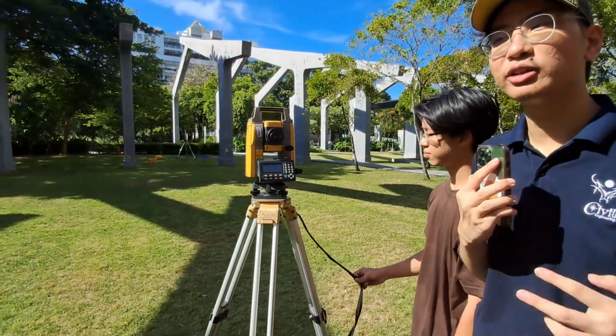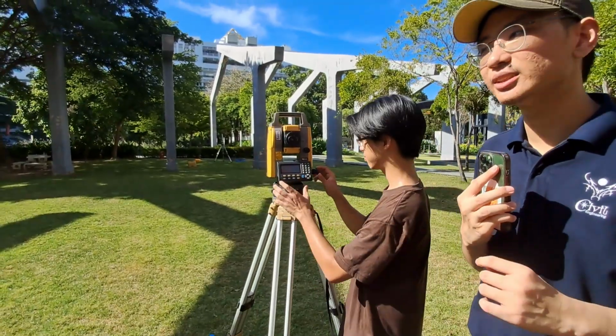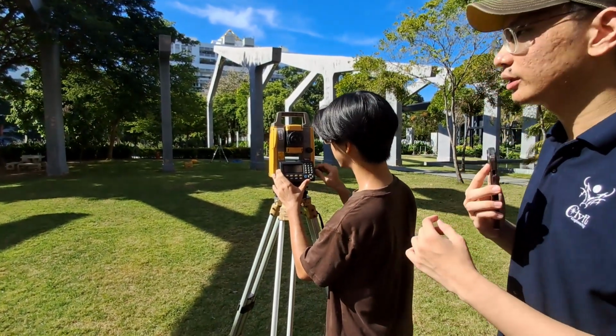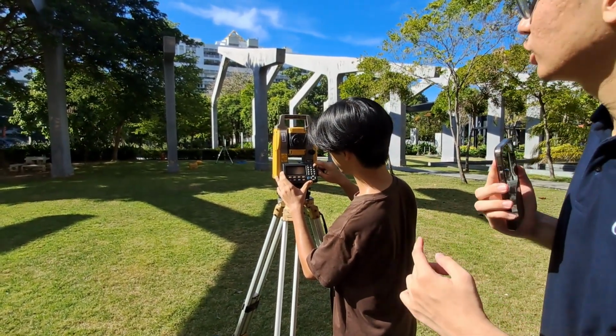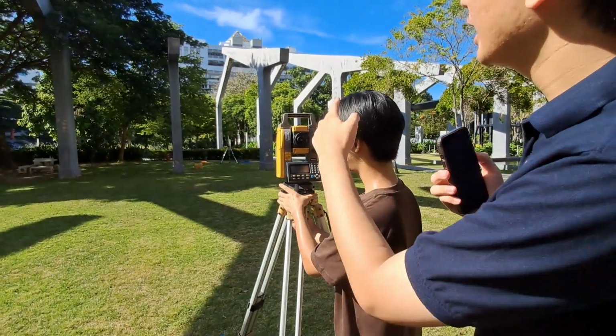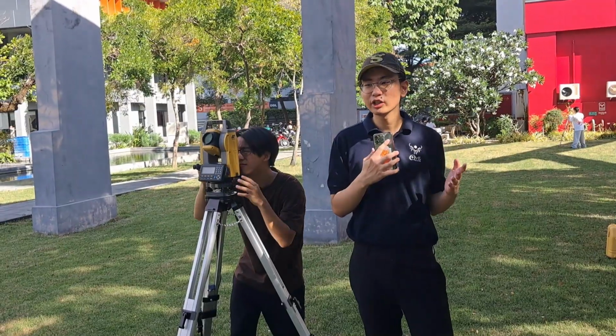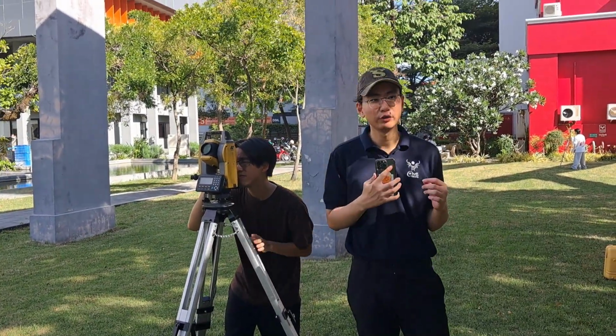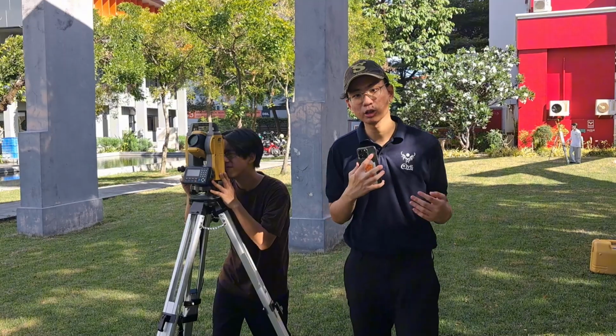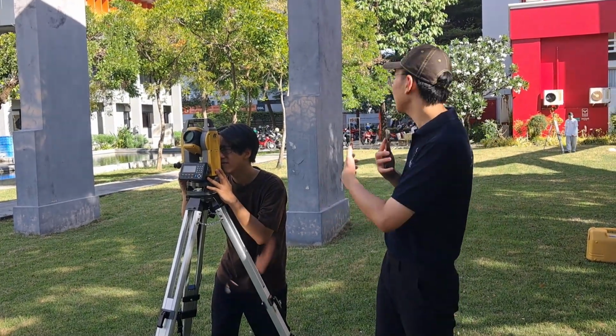And after we have done 2 of the angle measurements and the distance measurement, we can switch the place of the total station so that the total station will be set up at that point, and the prism will be moved to set up at this point. So after we switch the total station setup, we will measure another 2 angles, and also don't forget to measure the distance back to the prism as well.